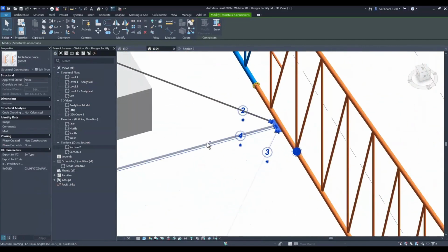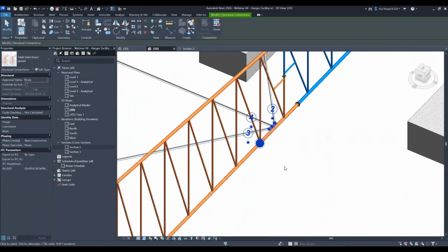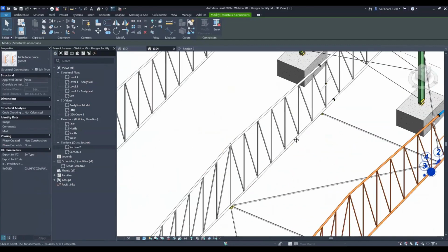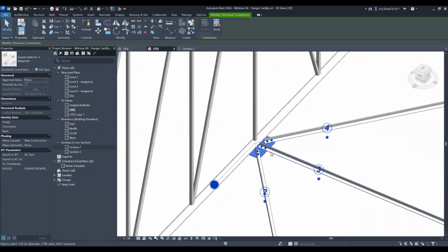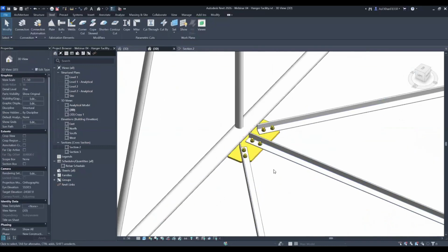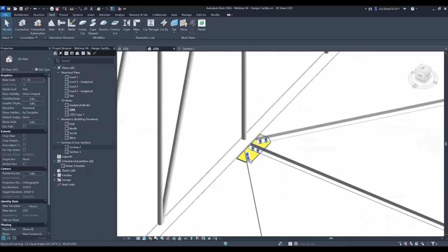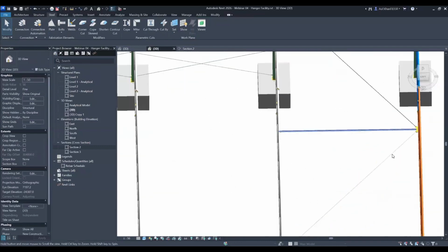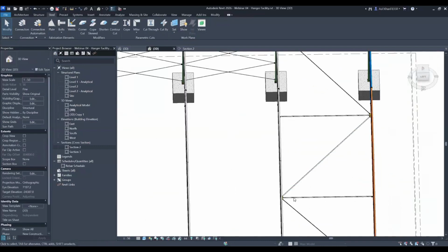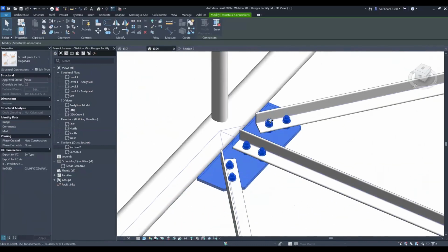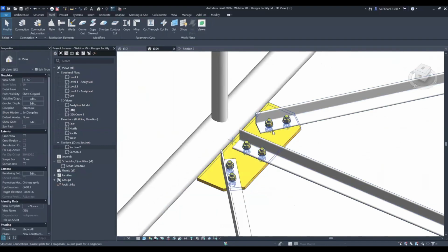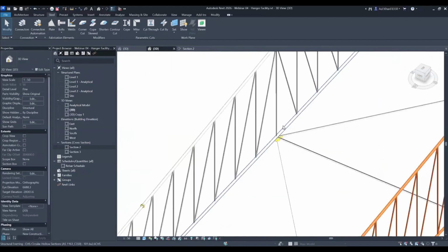And on the other side, I used a simple four connections, gusset plate for three diagonals. As you can see, different connection was applied, one with the T bracket, and another one is just simply putting them on a plate and just bolting them as much as you want. If your project says 3 bolts, 4 bolts, you can just apply. Your plate size and shape will adapt automatically.